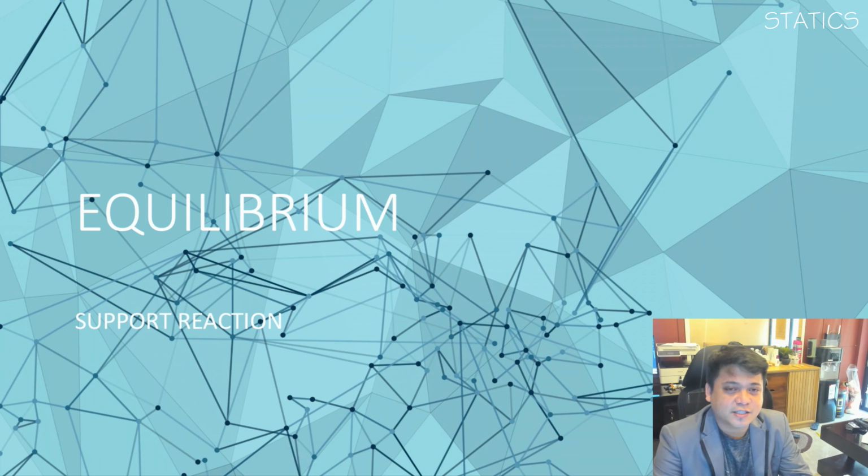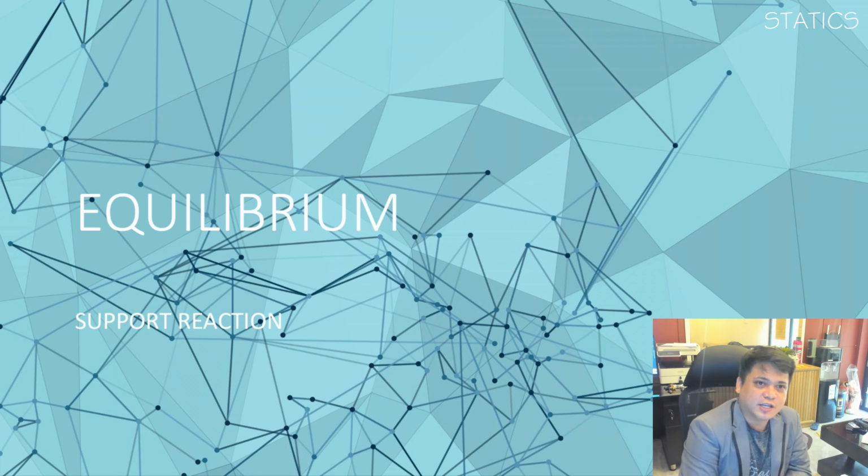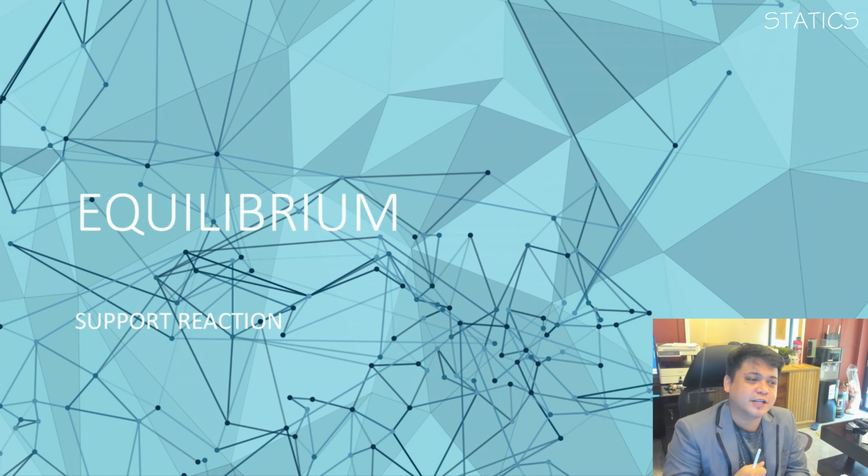Okay, so in general, we have six degrees of freedom or reactions. We have the forces at X, forces at Y, and forces at Z. That is the direct forces. And we have a couple, which is the moment at X, moment at Y, and moment at Z. However, in planar or coplanar equilibrium, it will just be reduced to three. So we only have summation of forces X, summation of forces Y, and summation of moment at Z. So it becomes just three. Okay?